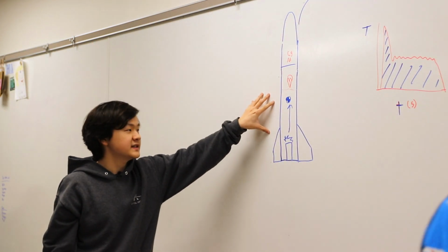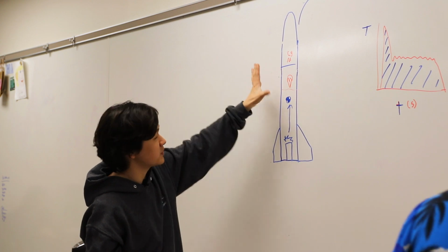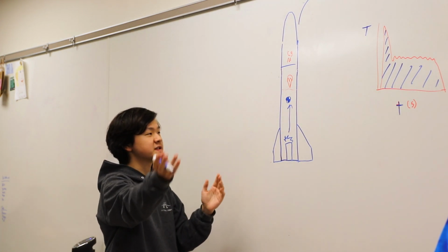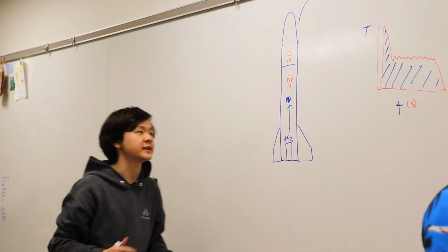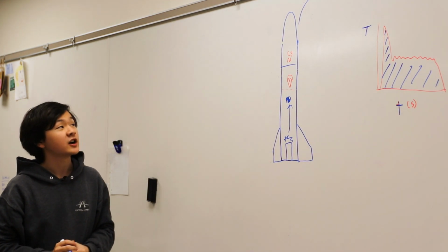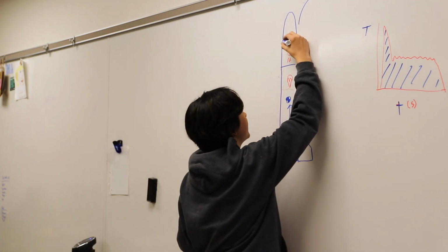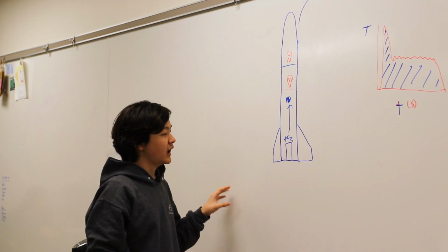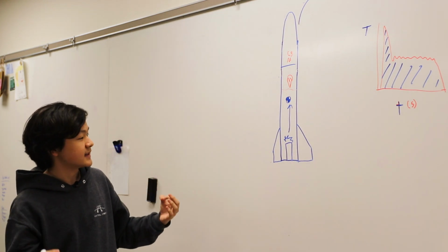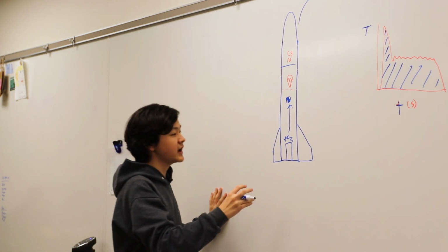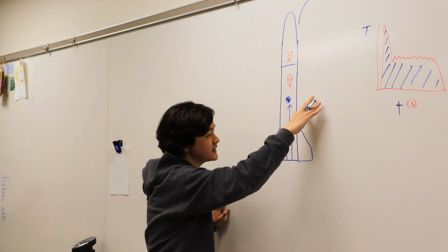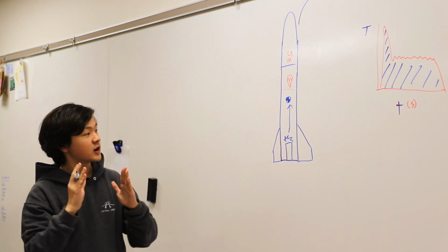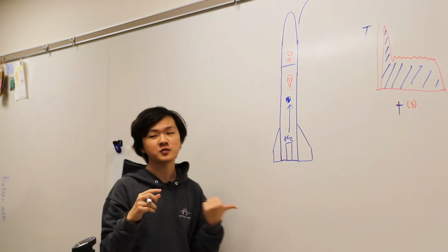This is basically the center at which the rocket will pivot if any sort of force tries to pull it sideways. Then you will have your center of pressure, and this is modified through the shape of the fuselage and the fins. As I explained earlier, as the air presses onto the fins, it puts an angular momentum on it.